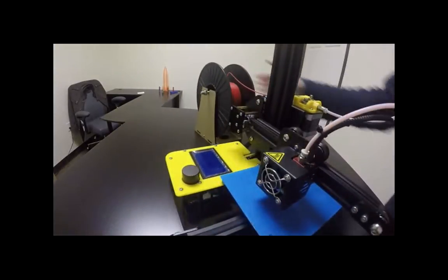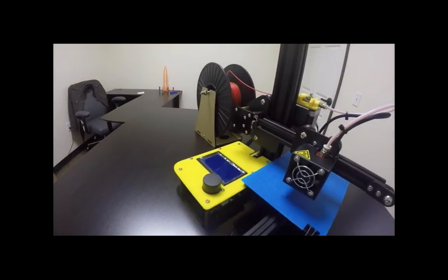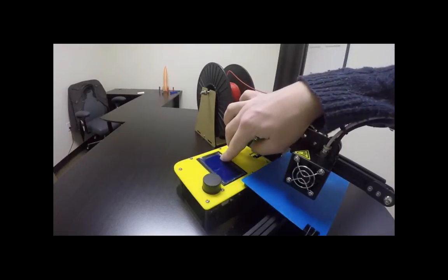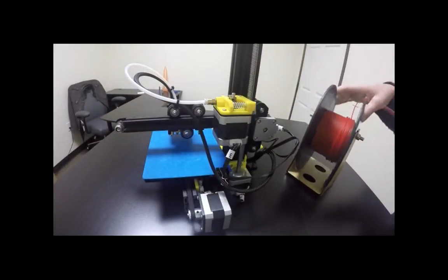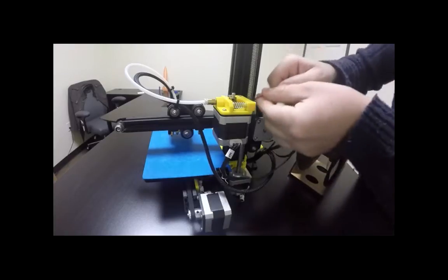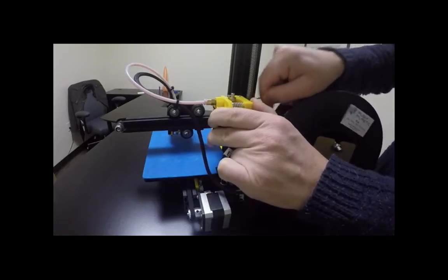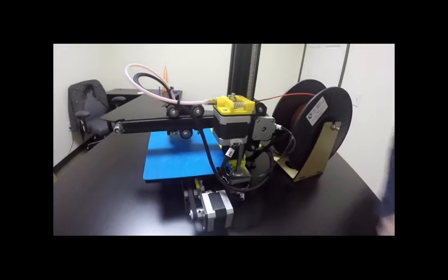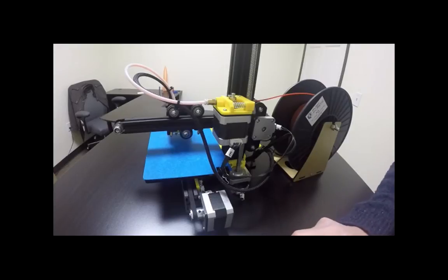So if you were going to unload the filament, you'd unload it when it gets to 100. You always want to unload it as it's heating up and it says 100 degrees on the bottom. That's when you unload it. And you'll unload it by just squeezing this and then pulling it out. But it has to be at least 100 degrees because it's melted into the end. If it's not heated up, then it won't be able to pull out. And you want to pull it out at 100 because that's called a soft pull, and that will help prevent clogs. So if you always change the filament when it's at 100 degrees and pull it out right when it's rising up and it gets to 100, that'll help prevent a lot of clogs.